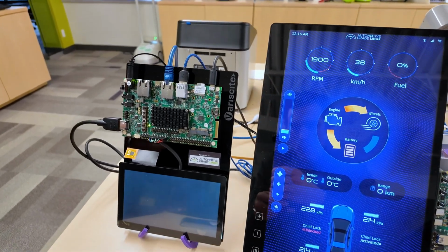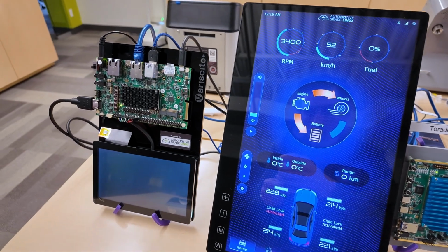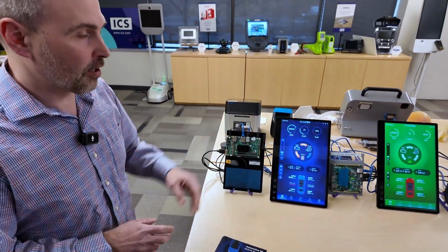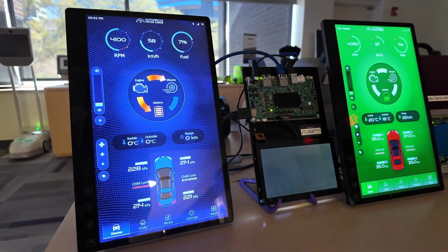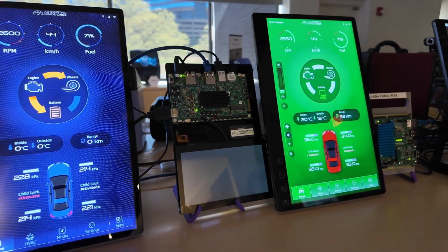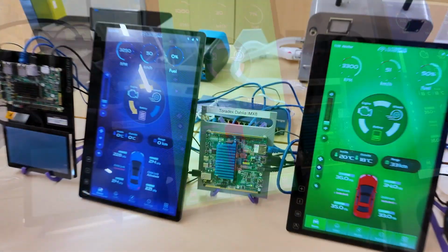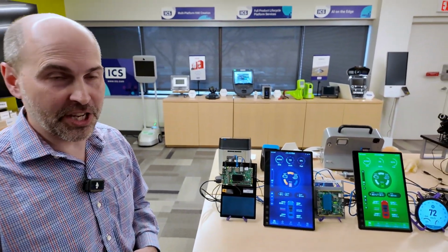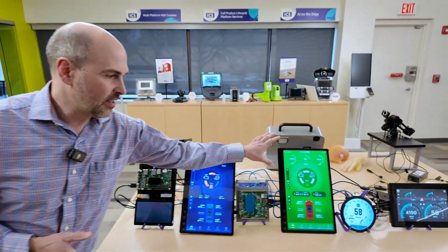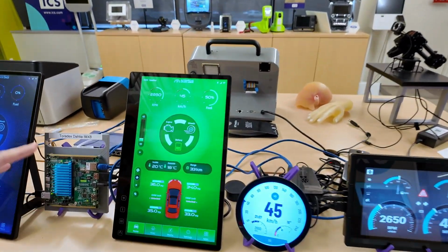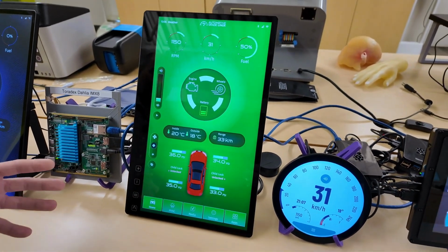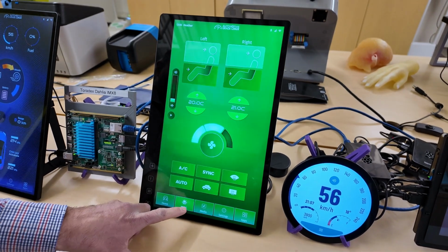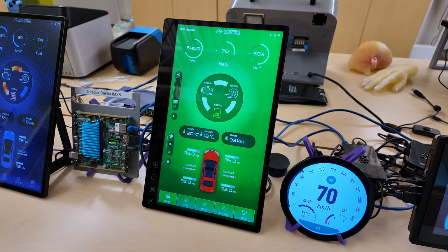Out of the box, AGL supported the Raspberry Pi and the Renesas R-Car, and we ported it to run on this Variscite IMX8 Dart and this Toradex Dahlia IMX8 MP. Then, to show off some of the toolkit agnostic features of AGL, we re-implemented the user interface, which you'll see here to the human eye simply looks like the same design but green and a different background. And it has feature parity with the Flutter version, except this is written in the Qt toolkit.